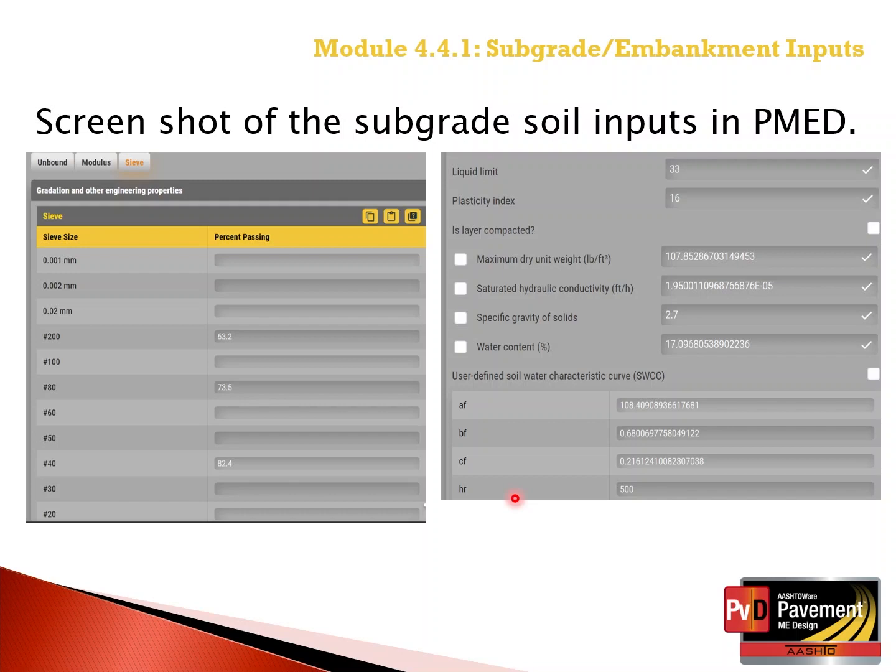If input level 2 resilient modulus is used or entered by the designer, it is important to remember that the dry density and water content be consistent with how the regression equations were used to calculate resilient modulus from one of the surrogate tests like CBR, R-value, and other test procedures. This point will be discussed in greater detail in our latter section of this module.